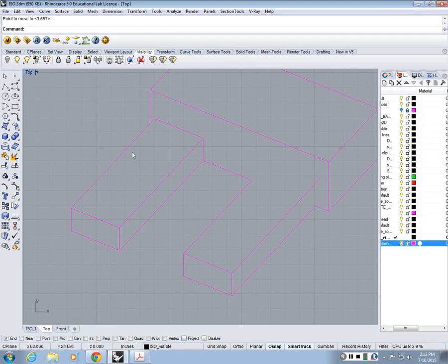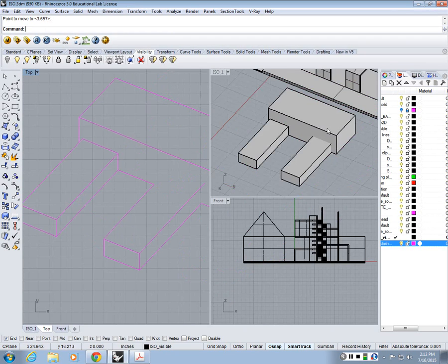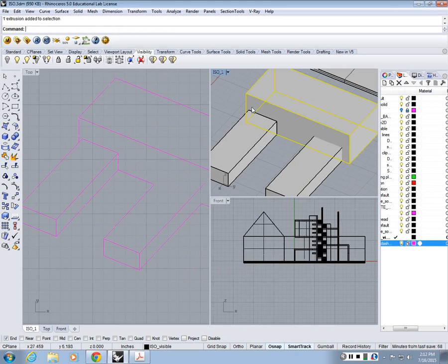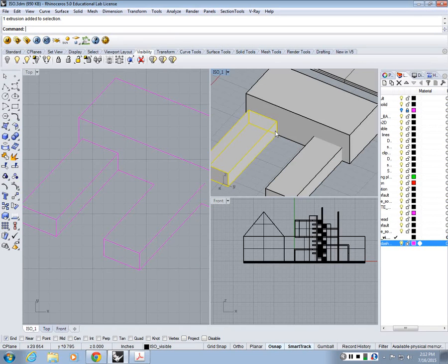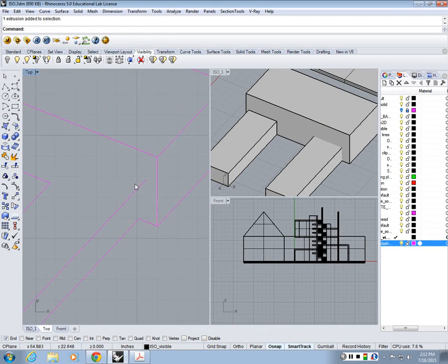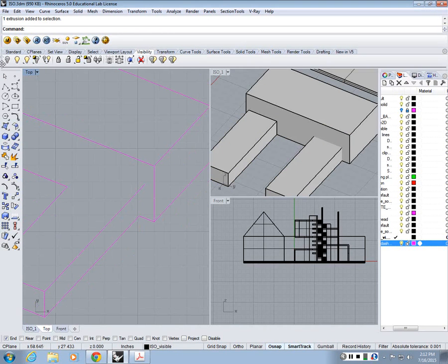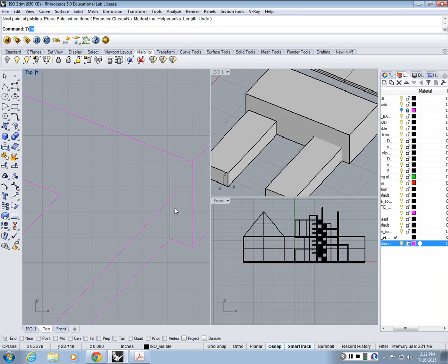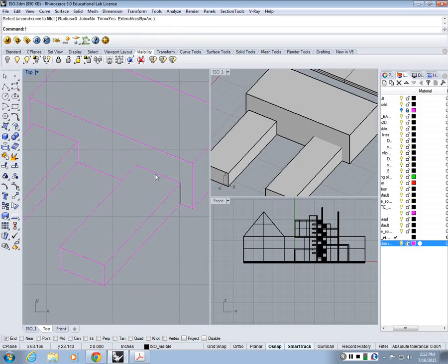Because this guy didn't intersect. This was the situation I had in the 3D model. This is the way it should be correctly modeled, the one on the left. So they're sharing an edge and a surface here, so you get these outlines. But here it's intersecting. So if you have something like this, what you could do is look at the 3D and then try to draft it here, right? So this will be trimmed. And then you can grab onto a parallel line here and then do fillet to this edge. So you can basically connect or plot these edges.